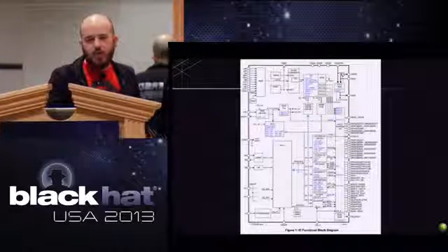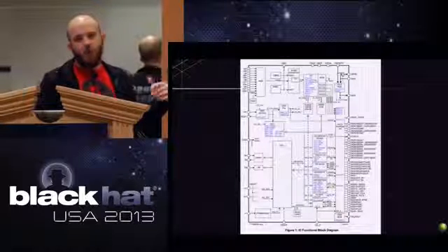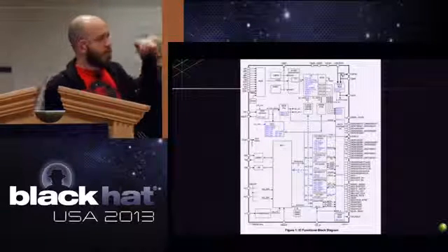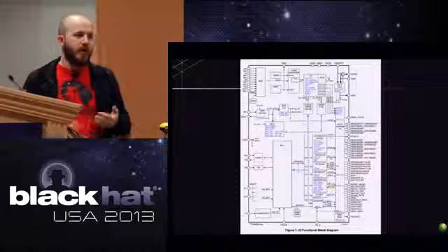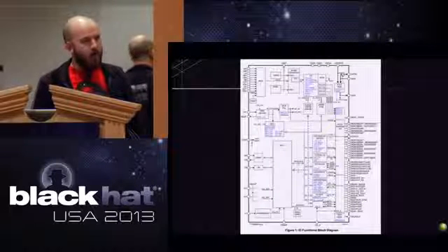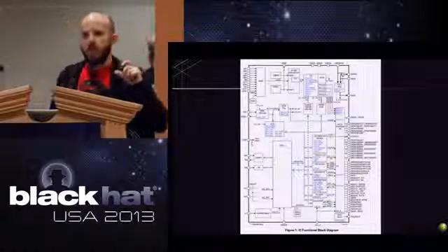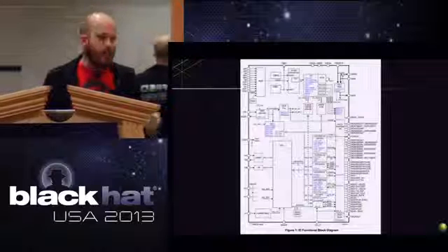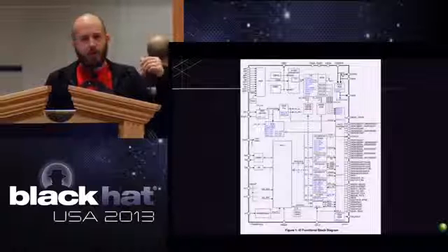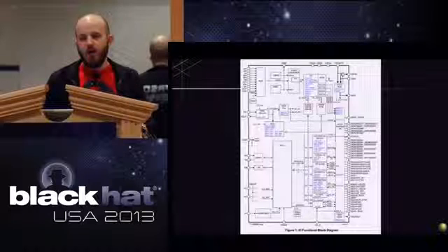So this is the overall schematic of what is inside that SoC, right? A SoC's got everything that would be needed for a given use case. In this case, we're talking smart meters. So it's got stuff to drive the LCD screen, and stuff to drive the pin pad that's on there. It has lots of inputs designed specifically for measuring power usage in an accurate manner for smart meters. Every single one of the Teridian SoCs has a very similar structure: an 8051 core, memory, and then different peripherals that they stuffed in for the different use cases.